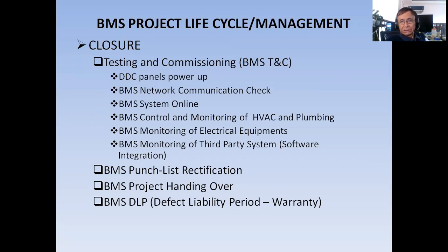Once all the DDC panels are communicating, that is the time to check if your BMS system is online. You have to go to your BMS workstation and check if the system is already online. When it is online, you will be able to see all the DDC panels communicating to your server, and you can see the different field BMS points.